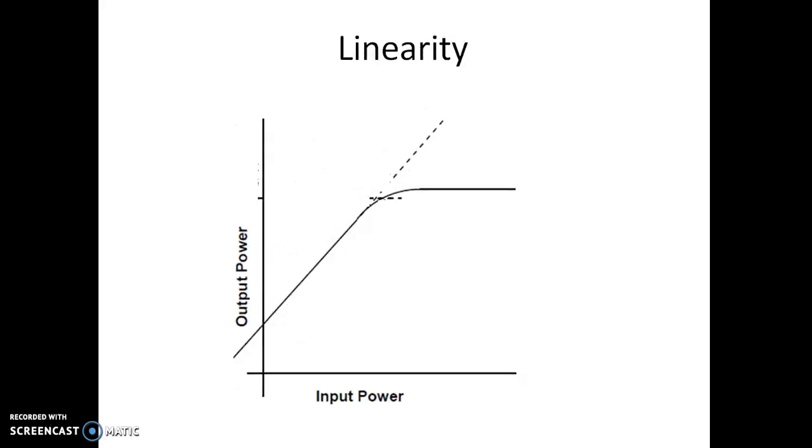So this is what we call linearity. We know that for all input power, we expect the output voltage to keep on increasing. But actually what happens is, up to a certain voltage, the output voltage follows the input voltage with whatever gain is specified. After some point, you can see the output voltage saturates. From here to here, we can say the circuit is behaving linearly. After that, the behavior is not linear, it will be a saturated one. So this is what linearity is.